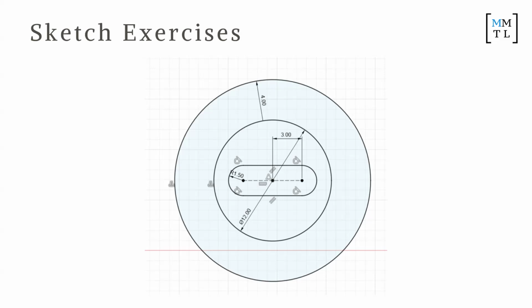No, that's okay. I've got red lines now. Yeah, but now you're not on the sketch one. So to orbit, yeah, that's a good start, create the circles now as well. And then go back. So there's three circles and then use the offset feature in order to create a larger circle. Offset. So I have to just create a new sketch and then it'll be in this grid line.